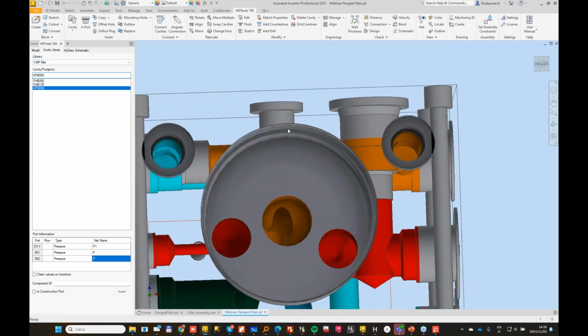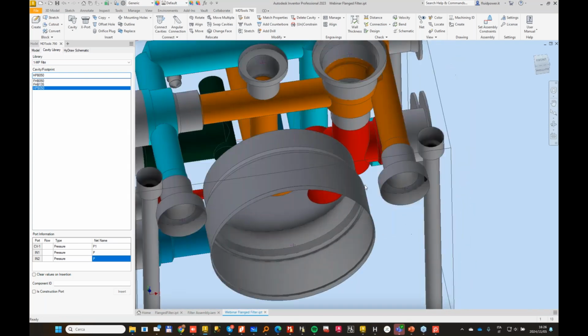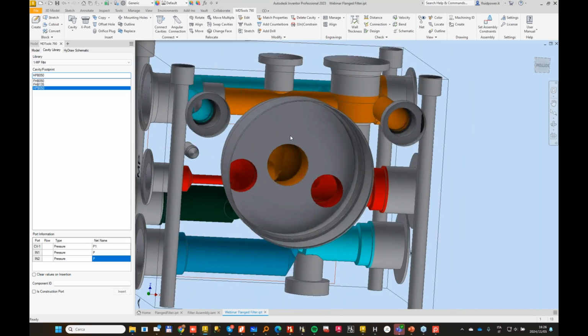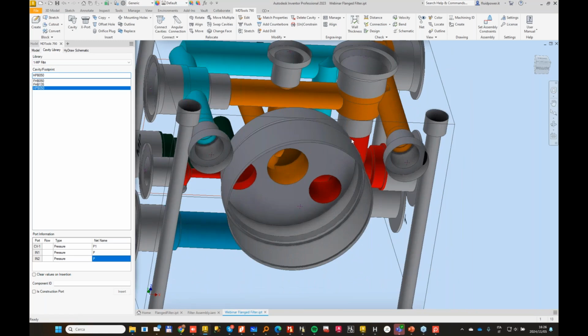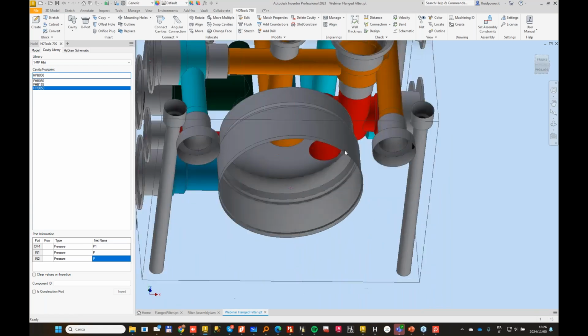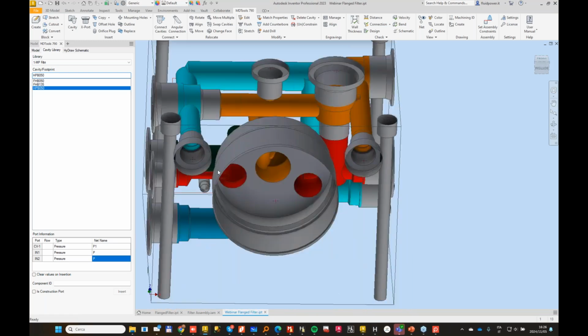Pay attention to wall thickness when you have very large drills, because, since it's a pressure filter, the pressure will act on a large surface. So it's better you pay attention with large drills. So better to have enough wall thickness.